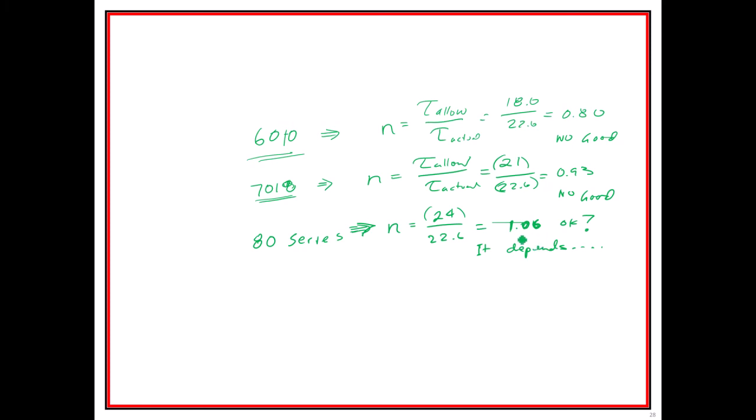Well, that 1.06 would have to be defended in a court of law. So it depends on what the application is. Don't depend on somebody else's safety factor. You need to dig deeper into it.